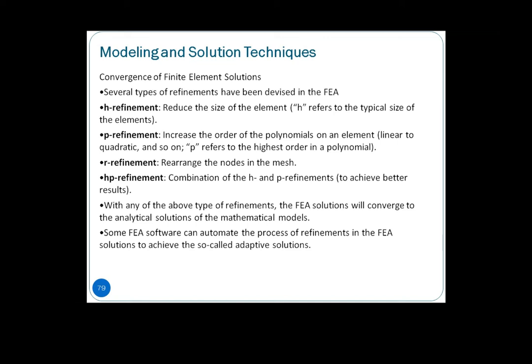Manual type: usually if you are performing a computational analysis, what we call finite element analysis, you are required to do this kind of refinement to, like I mentioned, find a cutoff point between the number of elements or the size of the element that you want to use to achieve relatively good accuracy, while the computation time is also reasonable.